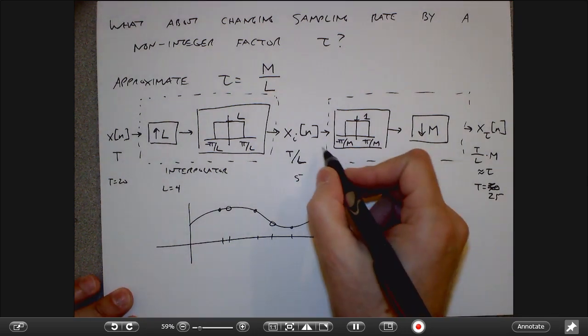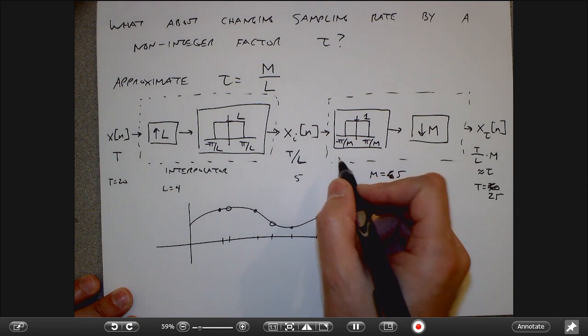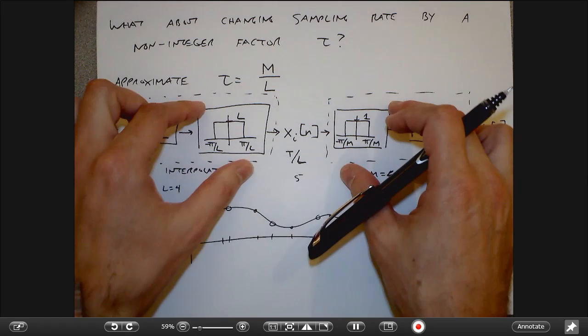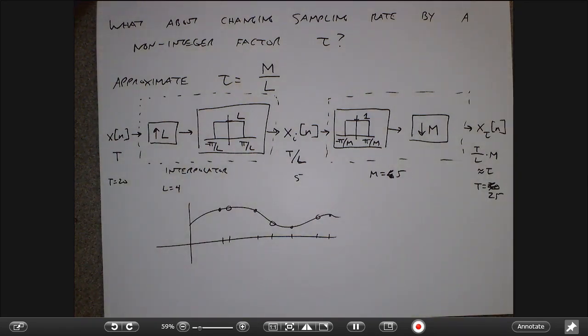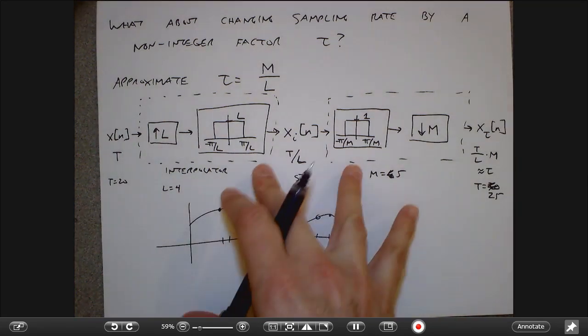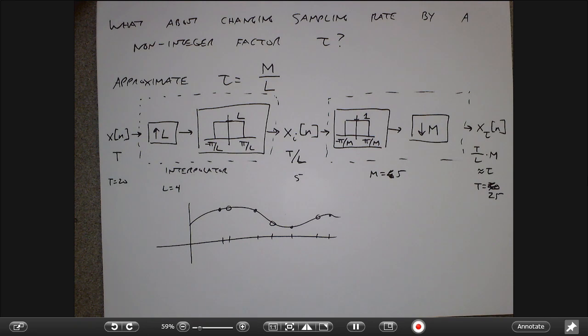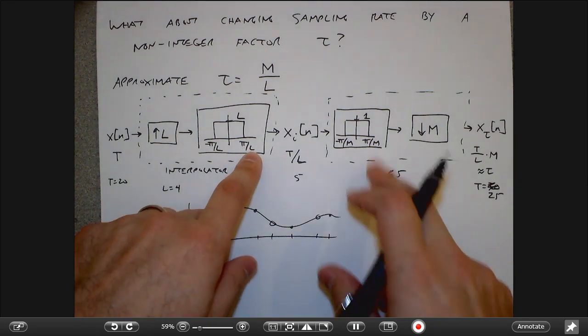And I can make a little bit of an abbreviation here, because here I'm passing the signal through 2 low-pass filters sequentially, right? So only one of these low-pass filters is going to be binding, right? Depends on whether L is bigger or M is bigger.